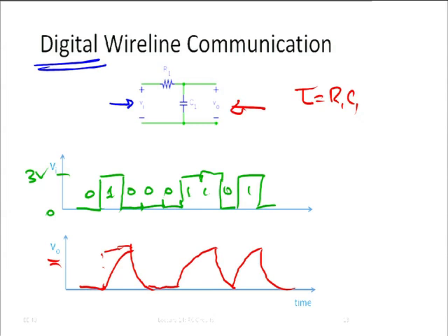Student: I can see when the voltage goes up to 1, the capacitor starts charging. How does it discharge? Where does it leak into the air? No, actually it's very simple. This voltage here, V1, is either going to be 3 volts, or it could be 0 volts. If it's 0 volts, then the current simply goes this way through the resistor, and it dissipates in the resistor or in the source resistance.